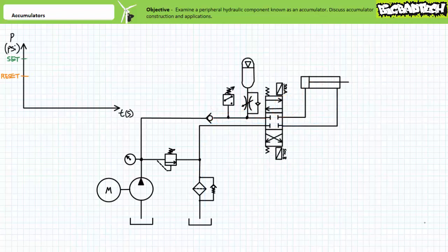Even without worrying about emergency shutdown scenarios, the accumulator in this same circuit can also be used to limit runtime of the motor-driven pump. Again, consider an actuator only infrequently used, for example, a hydraulically applied brake. Only when actively extending or retracting does the cylinder require flow. Otherwise, it can be placed in a static idle position.